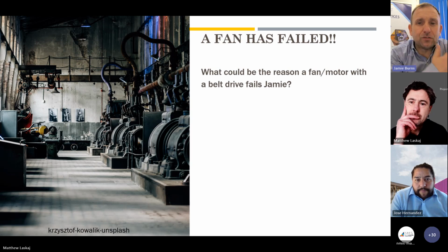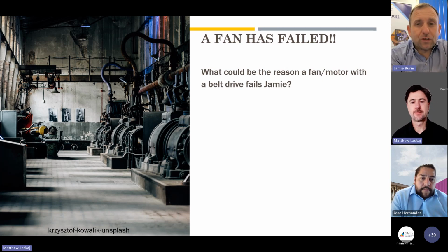It could have been out of balance. It could have been a bearing failure. Could have been the motor. Has it failed due to the mechanical element of it? Is it an electrical failure? So what's actually the situation with it just now? Will it just not start, or does it start and it's running, shaking itself around?